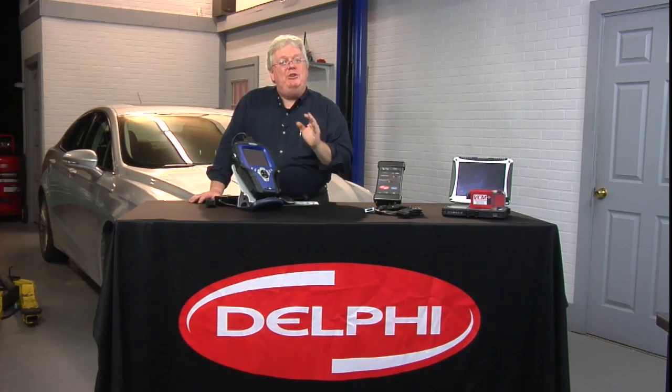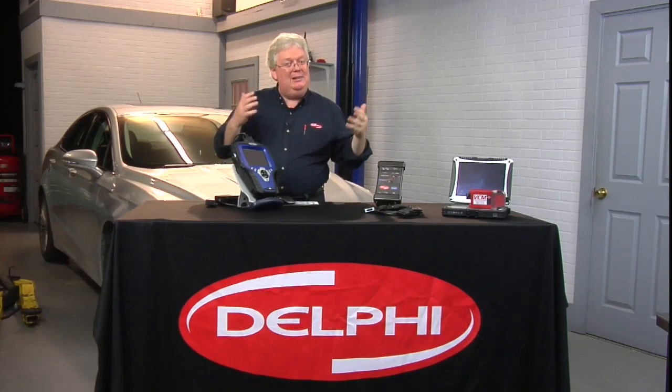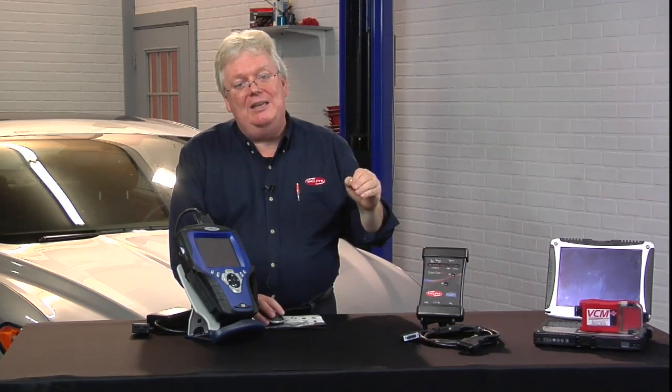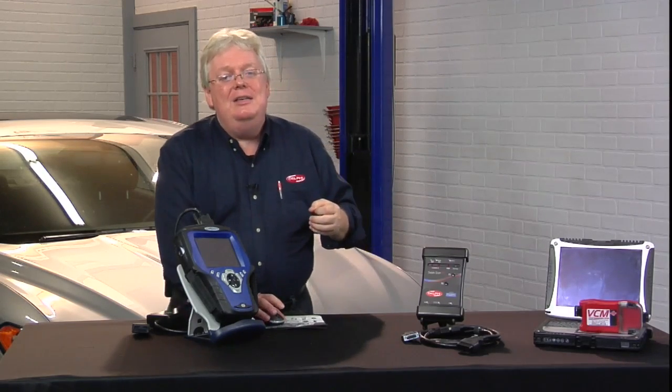Well, if you want to be top notch using things like lab scopes and mode 6, a high-end drivability shop, you want to be the best shop in your area, you may look into investing in a dynamometer, because you may have to get that vehicle somehow rolling to get the monitors. There are tricks you can do sometimes to force monitors to run, but for the most part, you really got to drive it one way or another.